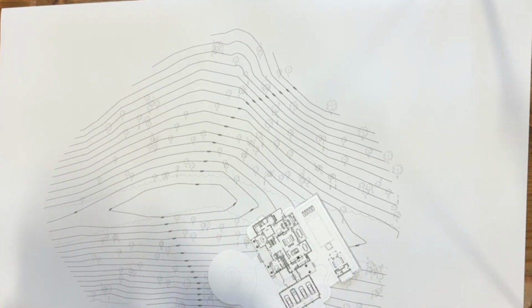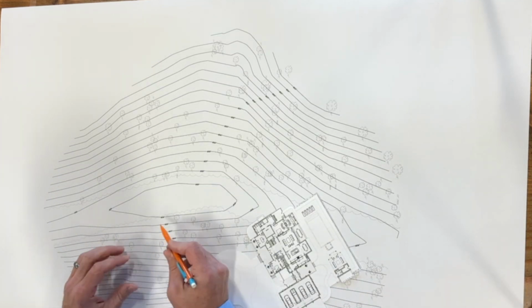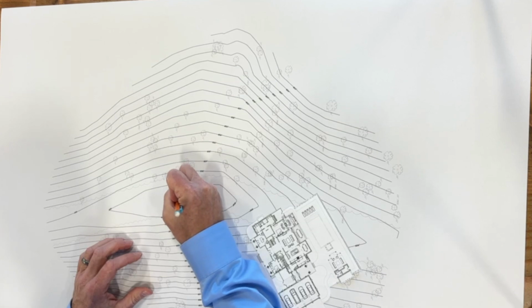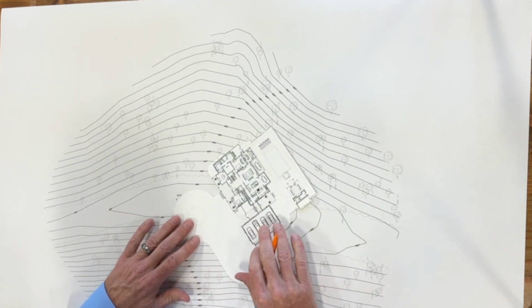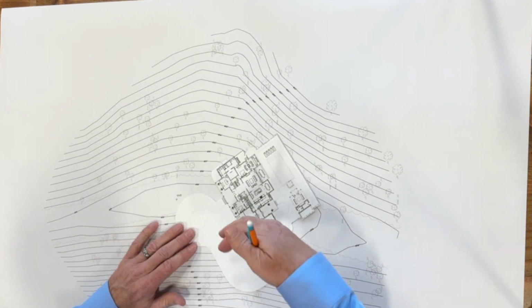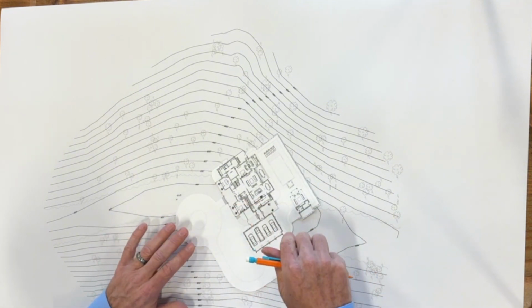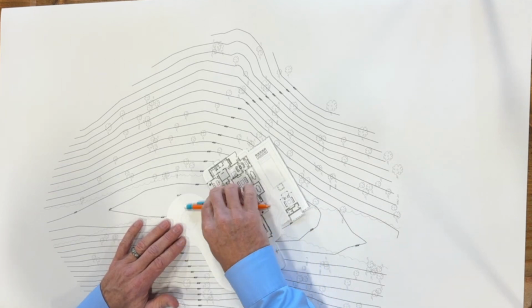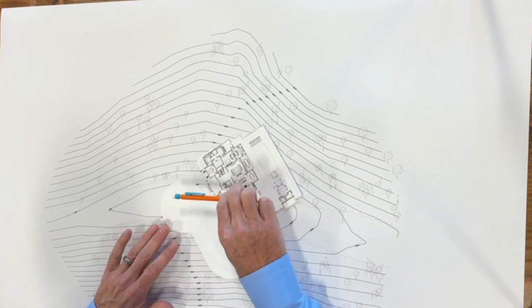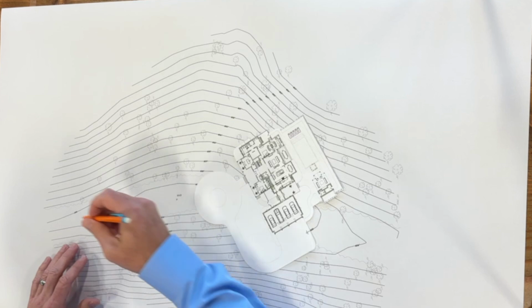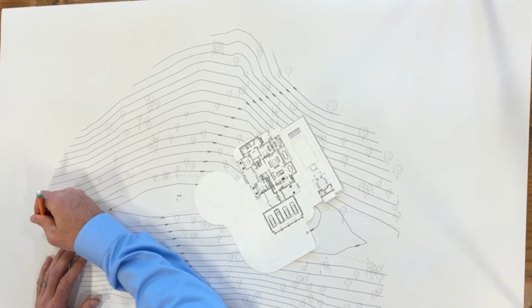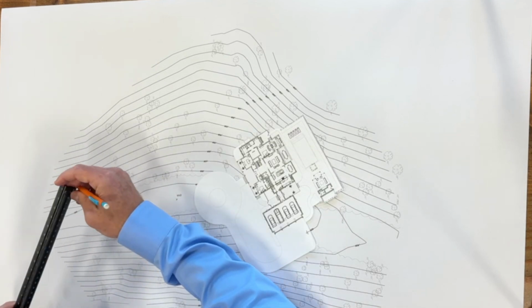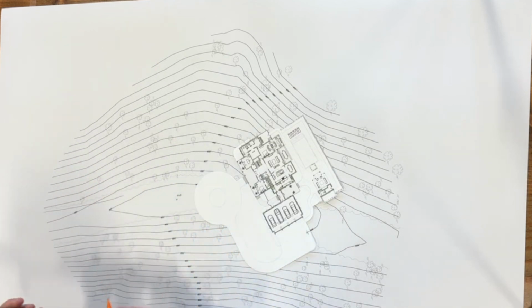This is, to give you an idea of the contour lines, this is 939. So right here in the middle, you can just assume is about a 940, right? So we're going to say that the middle of this whole thing, which all of this needs to be relatively flat, is kind of coming right through there. So I'm going to put that there. The other thing is the driveway is most likely coming in right through here. And about a 12-foot wide driveway is what we're going to figure. So that's a 20 scale.